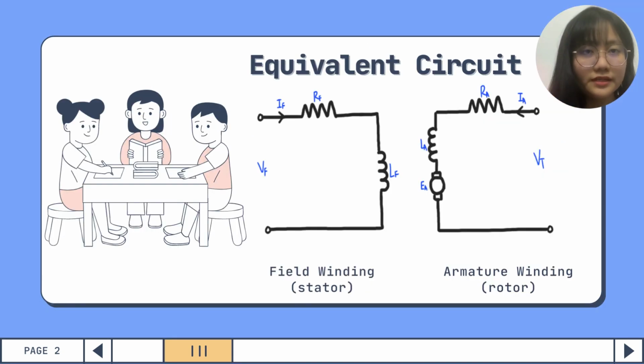In a separately excited DC motor, a separate supply is used to excite both the armature coil and the field coil. In the case of a separately excited DC motor, the main supply is given separately to the armature and field windings. The major distinguishing fact in this form of DC motor is that the armature current does not move across the field windings, as the field windings are powered from a separate external supply of DC.